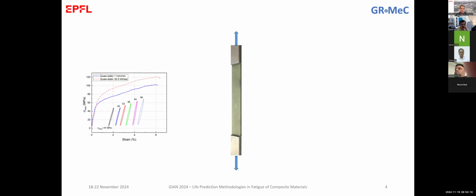And the second point that justifies the selection of this loading rate is that it is the same loading rate that we have when we do fatigue testing. It's an average loading rate that you can see. When you do a fatigue test and you are loading the material with a frequency of 10 Hertz, for example, the speed of testing when you go through this spectrum is relevant to this value. And if you compare the loading rate between these two static tests, the fatigue testing is usually, for more or less all the frequencies that we are using, much, much faster than the quasi-static testing.